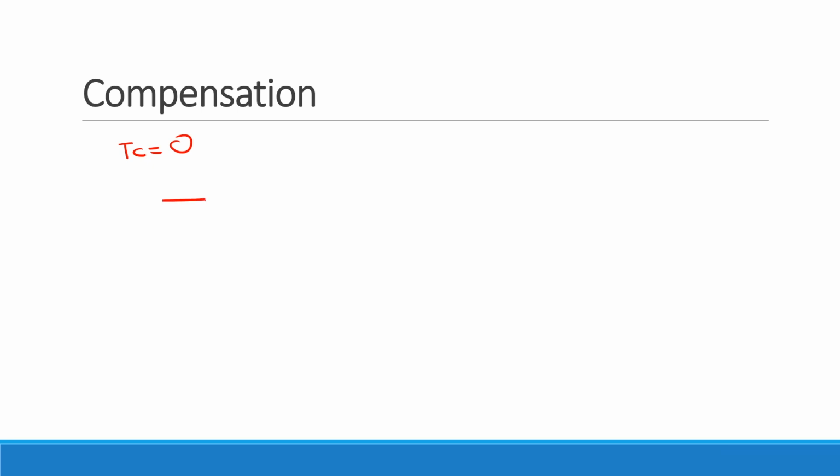If I get one thing that has a positive temperature coefficient, and then I have a second thing that has a negative temperature coefficient, and I just put those two in series, I basically get something like 2 equations and 2 unknowns, right? So I figure out how big do I make that first R and that second R such that the total resistance is the resistance I want, but that the temperature coefficients of the two of them happen to just cancel each other out.